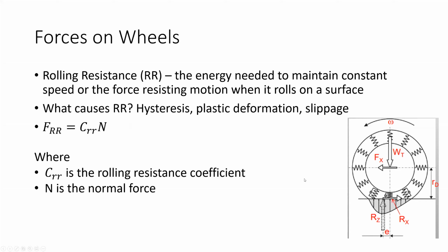There should be 3 moment forces: the center of gravity in the X and Y direction, and also the force on the rear tire here. That's pretty much that. And then if you want to find the grade resistance for the whole vehicle weight, you'd use this equation here, which is force is equal to weight times sine alpha.